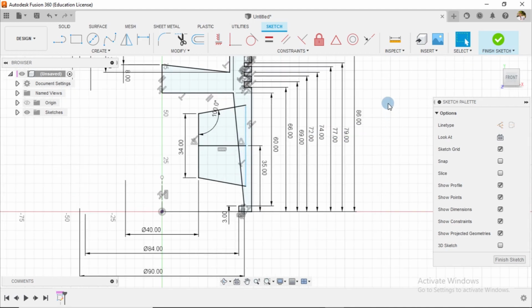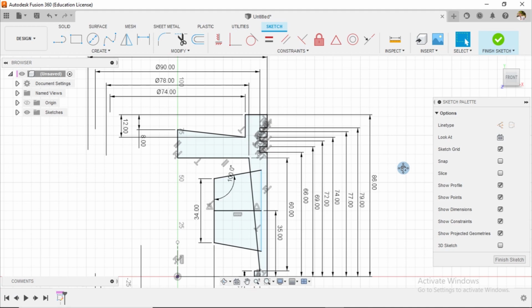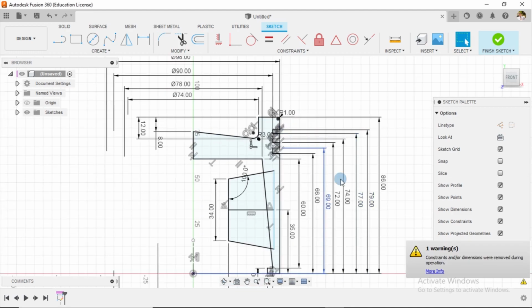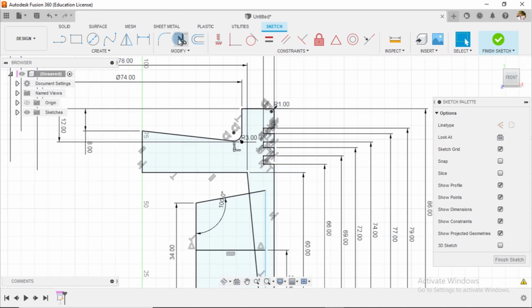So it's very simple. The next thing we'll do is apply fillets to this sketch. You remember that I've always said that my approach, which I think most people should adopt, is trying to use as few features as possible here. So this radius here is 1. I've inserted, and the radius we have below here is 3. Say enter. The warning here should be disregarded for now.